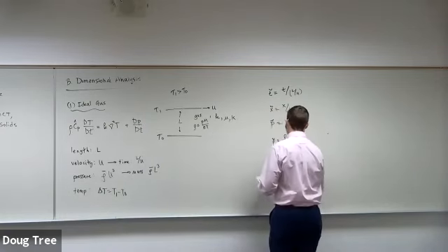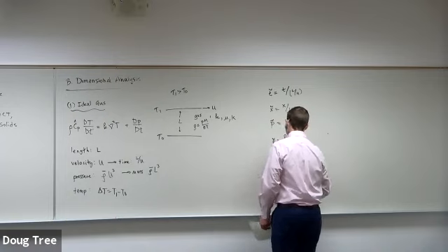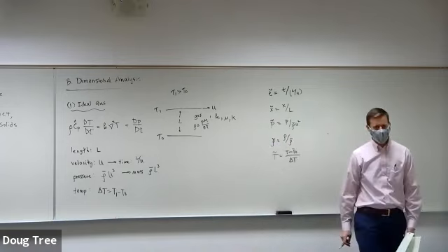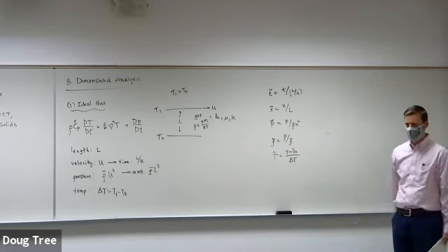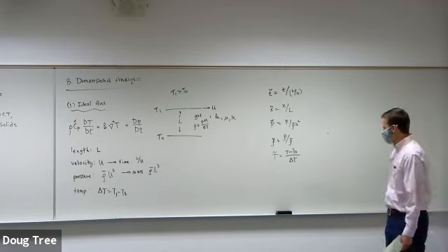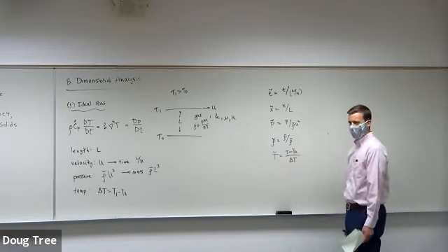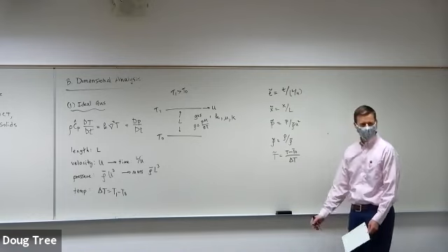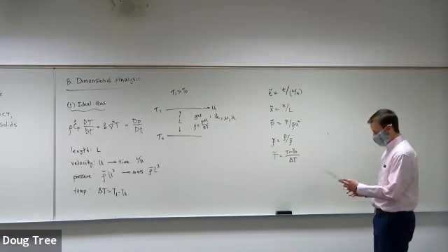We'll do that here too. We'll make temperature minus T0 divided by delta T. That makes it nice because then temperature will go between 0 and 1 instead of whatever other thing it does. So it's not just a pure ratio, I have to subtract. Temperatures are kind of weird like that, but that works out pretty easy usually. When we take derivatives, it doesn't matter to have a constant.